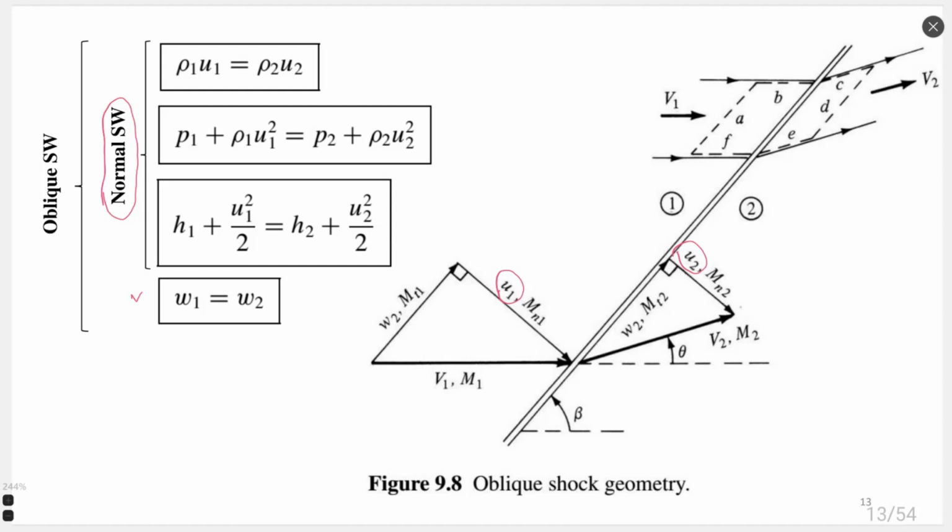And after, we just need to join back these vectors of tangential velocity component before and after the oblique shock wave. So 3 steps. Step 1, split velocity before the shock wave. Step 2, use normal shock wave theory to calculate the transition through the oblique shock wave. And step 3 is join back the vectors after the oblique shock wave. So a 3-step calculation. Very simple case.